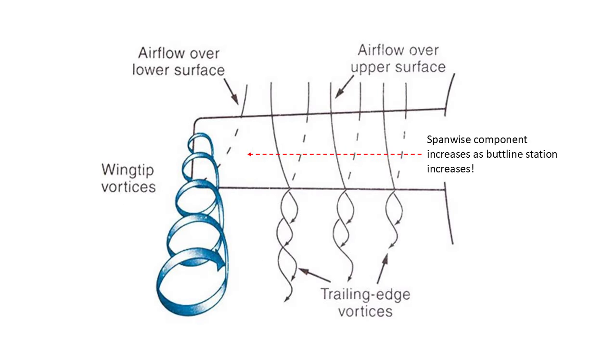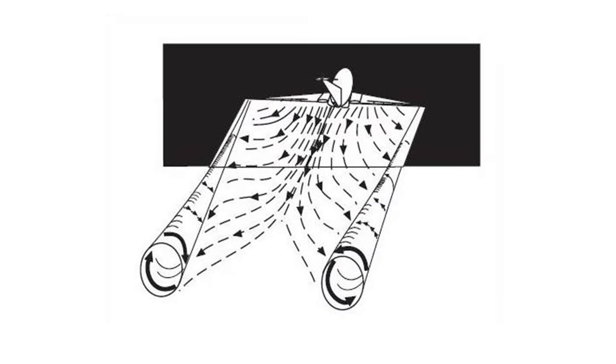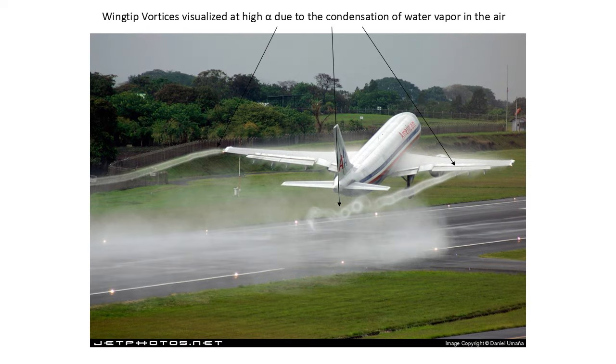It's also worth noting that the magnitude of these wing-induced velocities generally increase as we move outboard towards the wingtip. Anywhere along the span of this wing, these induced velocities will usually be highest just outside of the boundary layer, so relatively close to the wing surface itself. The pressure differential and spanwise flow generate vorticity along the entire span of the wing, which ultimately concentrates at the wingtip into two strong and well-known vortex structures referred to as wingtip vortices. You can sometimes see these vortex lines form on plane wingtips when flying in a region of high humidity.